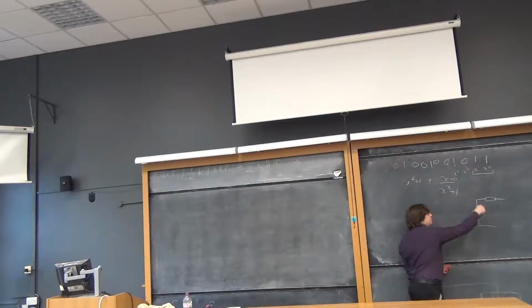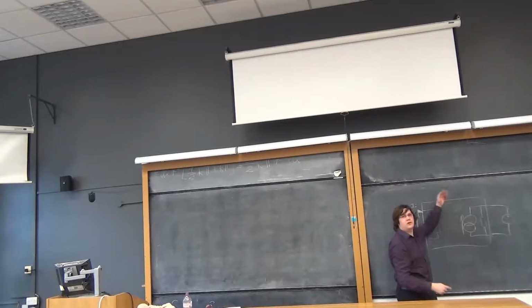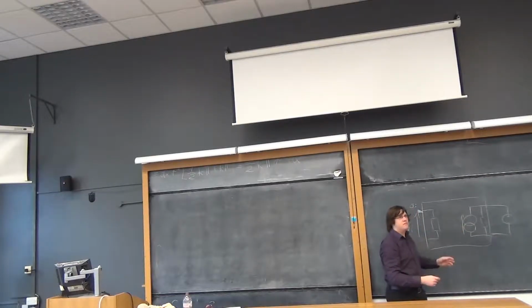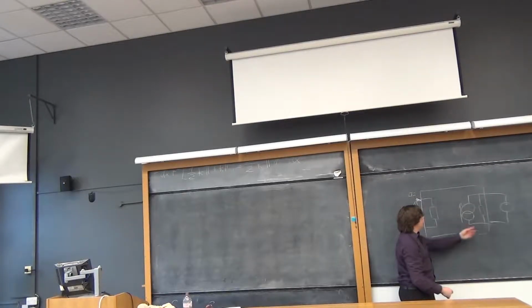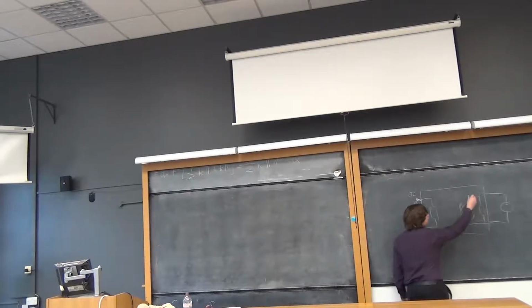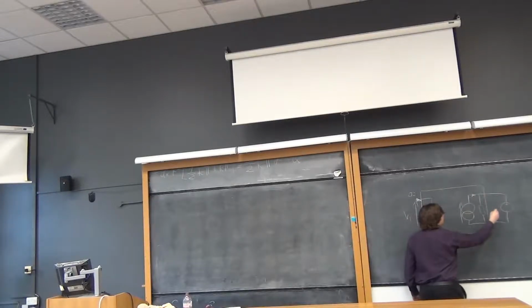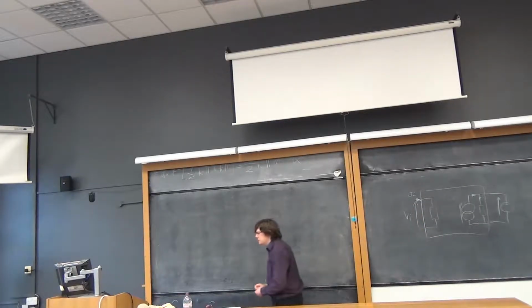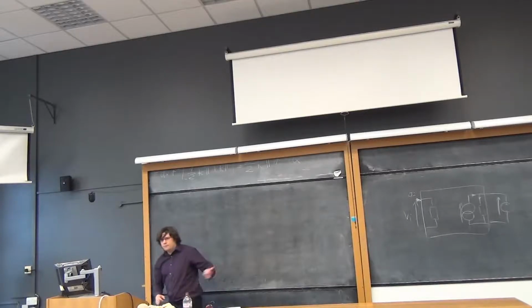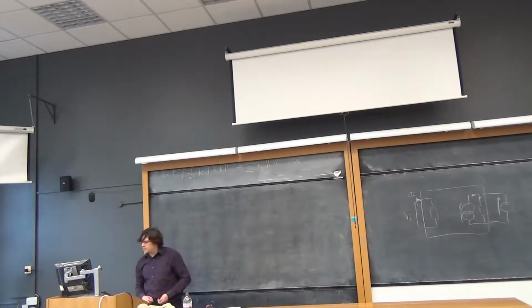Much as you can convert this to that by a transformation, which was given either in 117 or sometime earlier in the lectures. So if I wanted to know the value of this resistor, there's definitely some current leading there, but I can try to impose a voltage here, and the overall current will be the current that ends up going down there due to this minus that, and I can divide through and get R out. So that's what I mean by input and output resistances. That diagram's in the notes in a couple of slides.